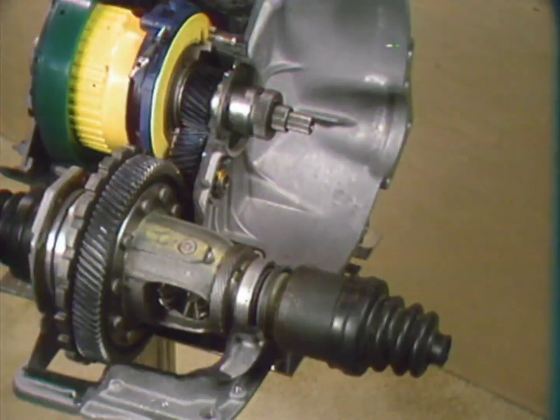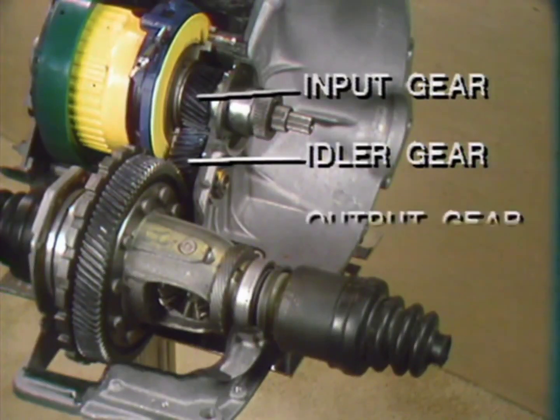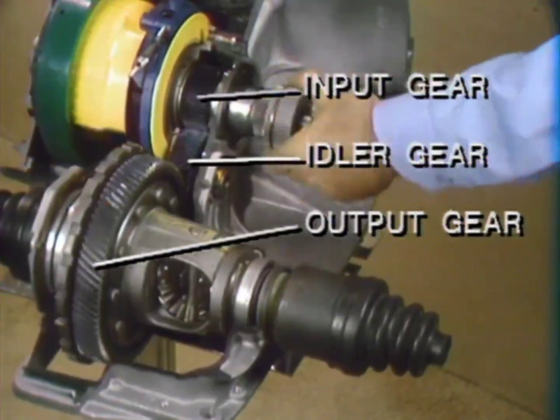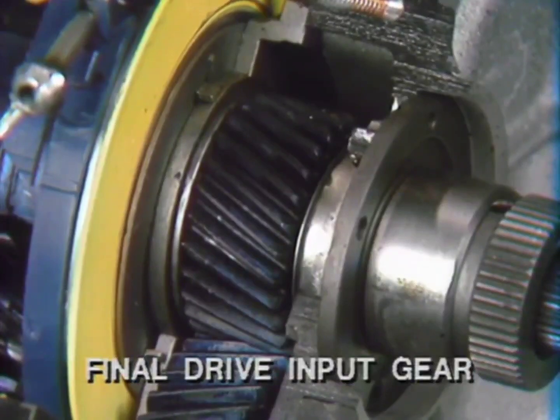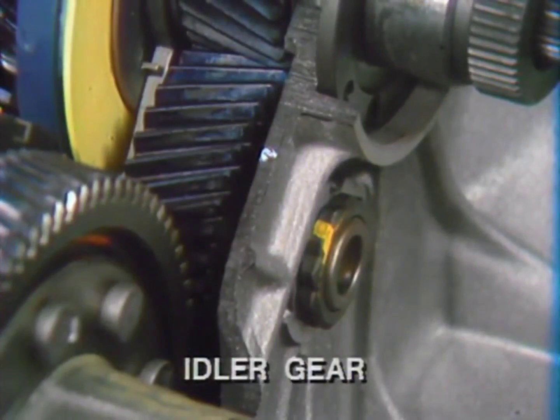From the main planetary pinion carrier of the transaxle, power is transmitted through 3 final drive gears to the differential. These 3 gears are called the input gear, the idler gear, and the output gear. They are always in mesh as shown and are always driven when the transaxle is in gear. The input gear, as mentioned earlier, is splined to the planetary carrier and always turns with the carrier. The idler gear is supported on a shaft between 2 tapered roller bearings so that it meshes with the input gear. Its only purpose is to reverse the direction of power flow.